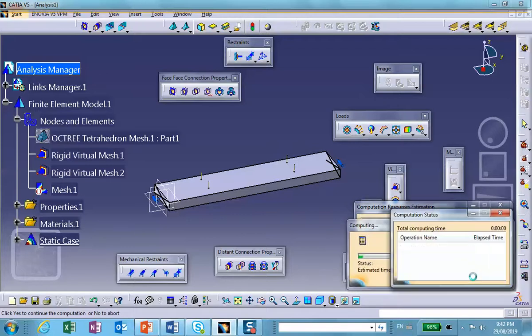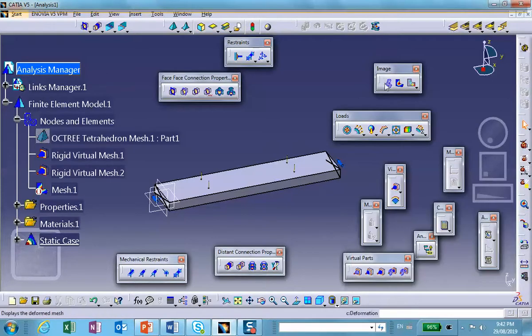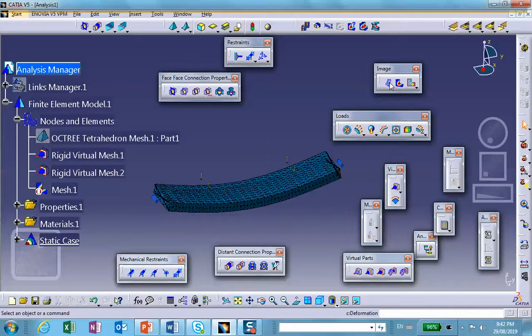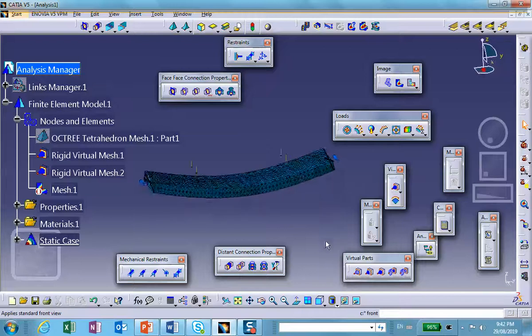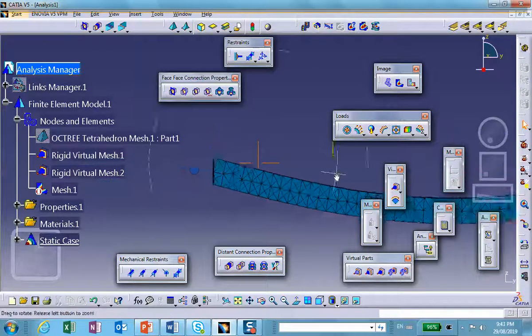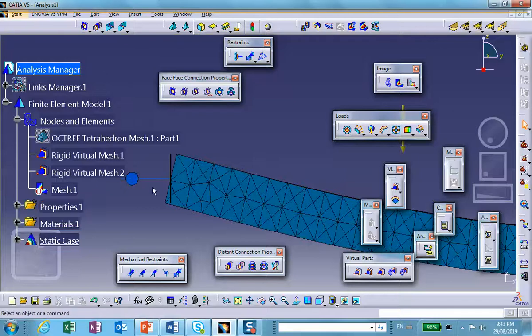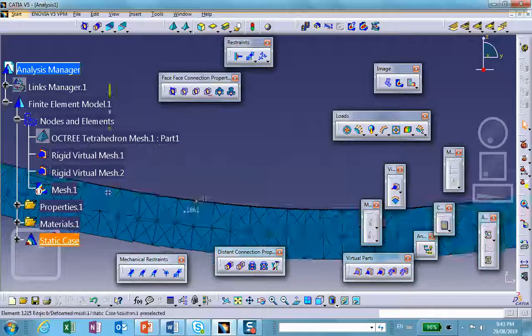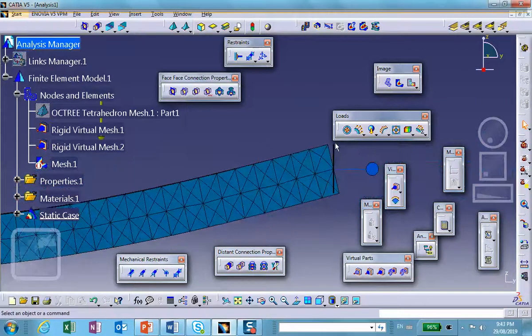Okay. So look at the deformation. Notice what happened is that if you look at the view from the front, which I believe is this, it's as if I have a hinge here that this plate can rotate about. But if you look at it from the top, the view from the top, same thing. By the way, on this side, you can see that. This was the original configuration, and it's rotated about it.